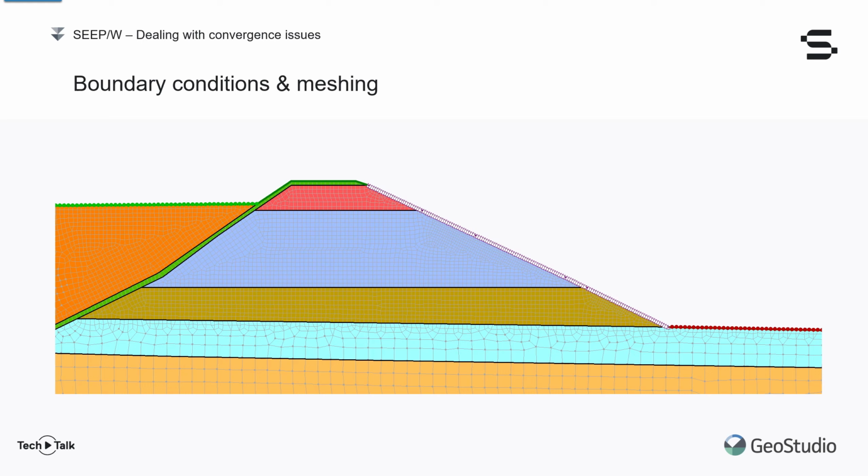There are three types of boundary conditions used. On the upstream side of the dam, a total head boundary condition is used to simulate the measured elevation of the water table. Having the boundary condition applied to the top of the tailings deposit instead of the far-field left side edge of the geometry is a bit unusual. I have chosen to apply it this way to better represent how tailing materials are deposited fully situated on the underlying materials, which decreases the depth of the water table, even very close to the dam.